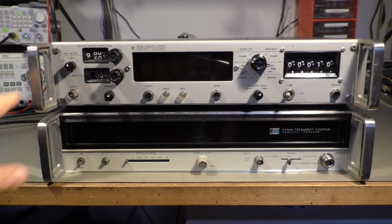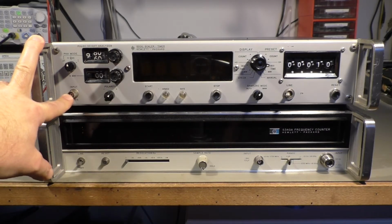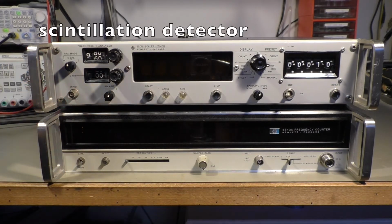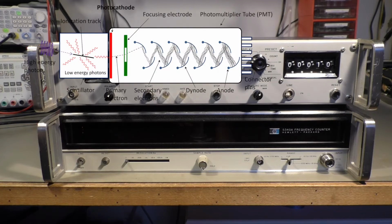So what it does is this: you attach a scintillator sensor to this input, and the scintillator sensor is basically a large crystal that reacts to gamma radiation, and every time a gamma particle or a gamma quant comes along and hits that crystal, the crystal emits a tiny little bit of light, and that light will be picked up by a photomultiplier tube and creates an electrical impulse that goes in here.